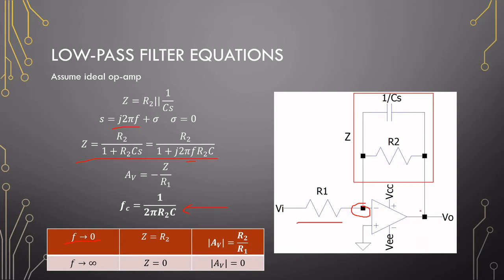Okay, so the way you could see this is if Vout is a low frequency, low frequencies will typically rather pass through the resistor, and we would find that we are working with a passband. If Vout is at higher frequencies, it will probably move more through the capacitor, since the capacitor becomes a short circuit at high frequencies.